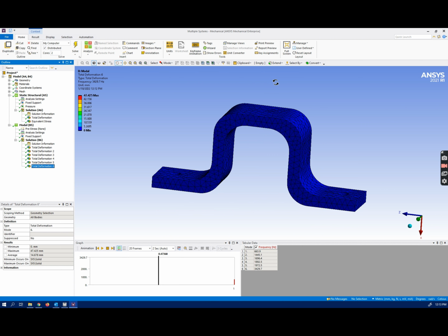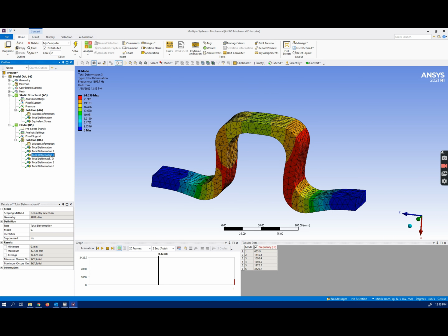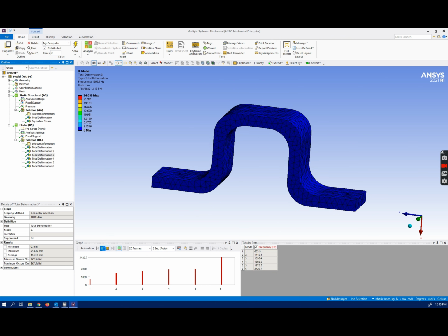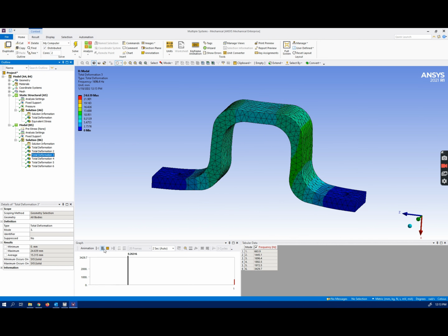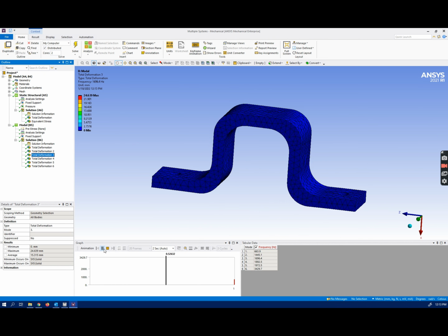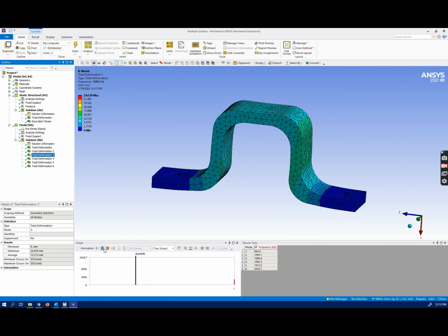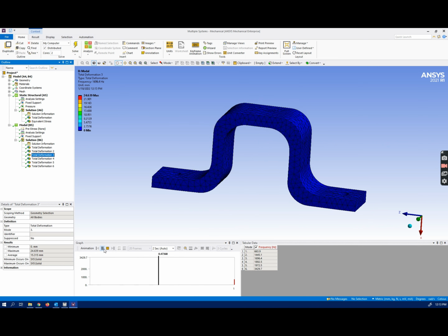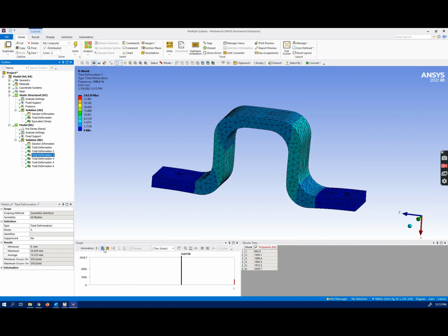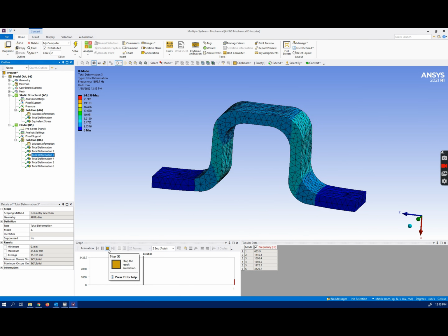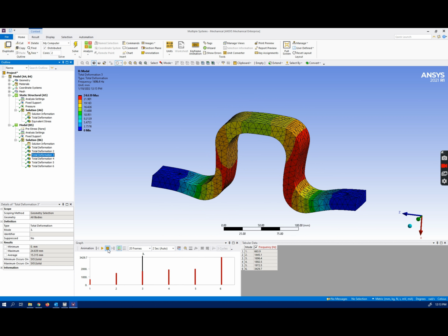We applied a vertical pressure at the top, so number 3 is going to be the frequency we are interested in. This one is vertically applied, and when I apply sinusoidal pressure at the top, we are going to have this type of vibration, and the natural frequency is going to be this one, the third one, which is going to be important, and we need to avoid. So number 3 is 1696. So we need to avoid this.